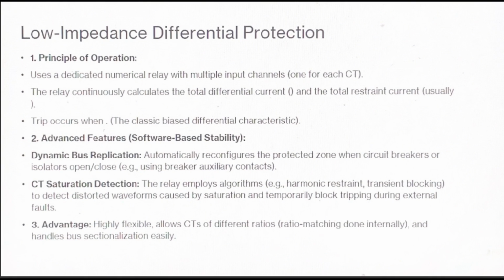And lastly is the low impedance differential protection. The low impedance scheme is the modern microprocessor-based approach, now the industry standard for new installations. Instead of relying on a physical stabilizing resistor, it uses software algorithms to manage stability.